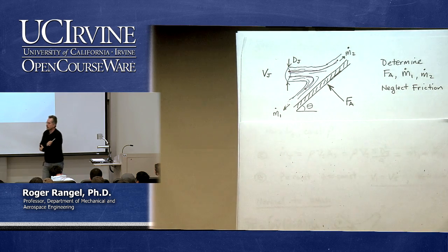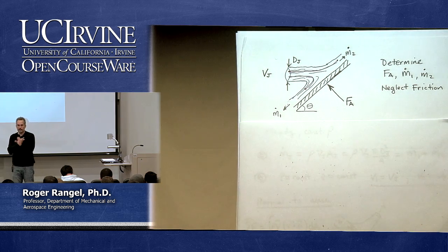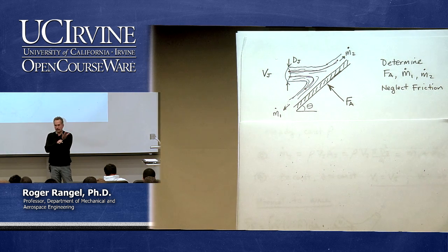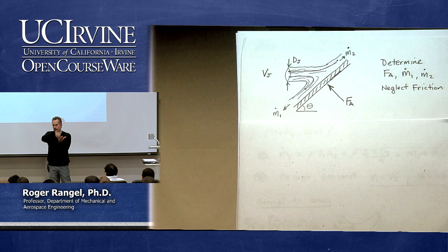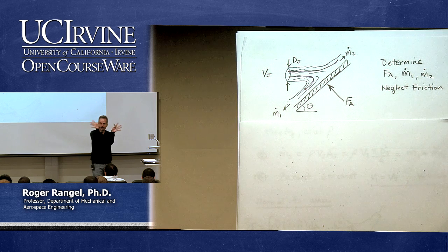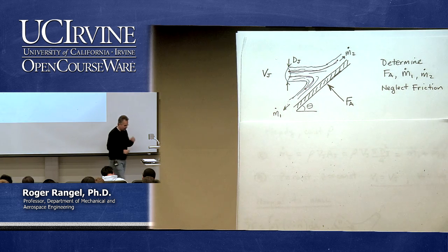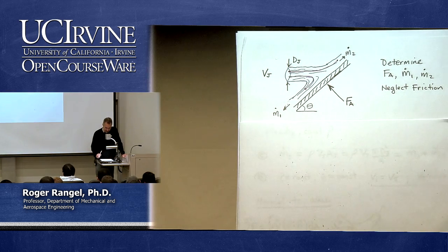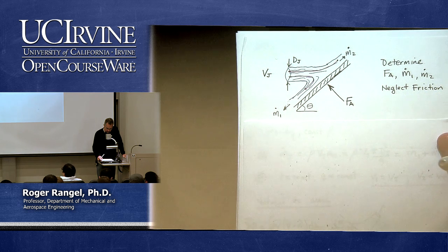That's a simplification, of course, because if it's a round jet hitting a wall like that, it would not branch out into an upward jet and a downward jet. It would actually have like a fan of water going in all directions. Right? But we're going to make our life easier by assuming that it just branches into two. That's a simplification, but it's to understand how to use these equations.